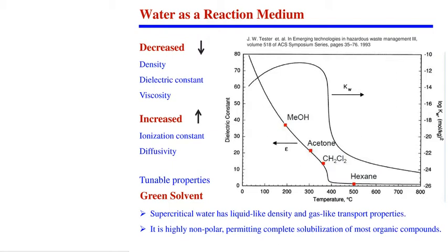How can we use this? If you see the temperature versus pressure condition here, in the low temperature zone, between let's say 150 to 250 degrees C, we can use this water, which is subcritical water, good for ionic reaction, to extract many important bioactive compounds, like protein-based compounds or valuable antioxidants. At a slightly higher condition, we can liquefy biomass and make bio-crude.